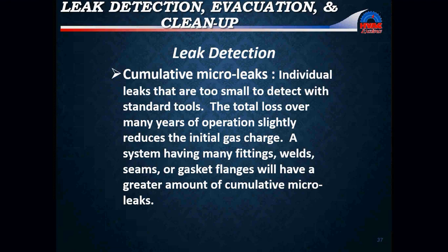Oil blotches can originate from motors, pumps, and other sources, or may be the result from residue from a previous leak. Oil is not always present at every leak, though. It may take months, even years of operation to cause enough oil to blow off to accumulate on that outer surface.